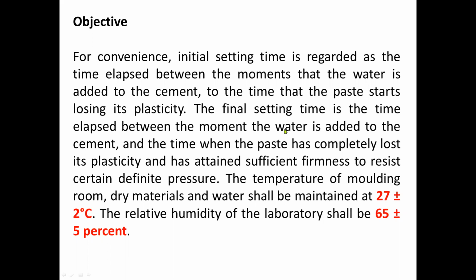The temperature of the molding room, dry materials, and water should be maintained at 27 plus or minus 2 degrees Celsius. The relative humidity of the laboratory should be 65 plus or minus 5%.